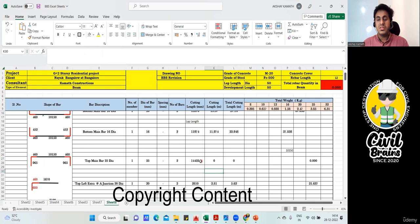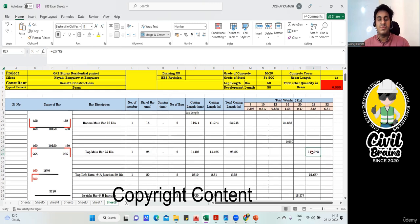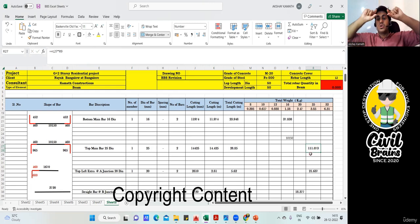Now to put this in meter, I'll select this and divide it by 1000. So 14.425 is my cutting length of one bar. So total cutting length will be 14.425 multiplied by 2 into number of member will give me 28.85. It's a 25 diameter bar, so I need to put this in 25 diameter column. And then 28.85 multiplied by 3.85 will give me 111.073 kg of steel. Done. So bottom bar I did, top bar also I did.